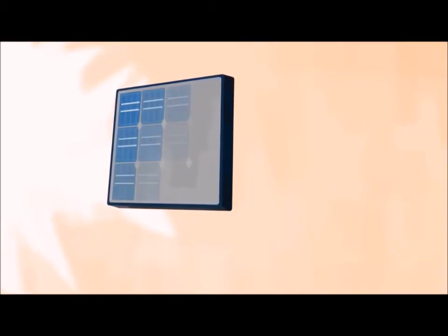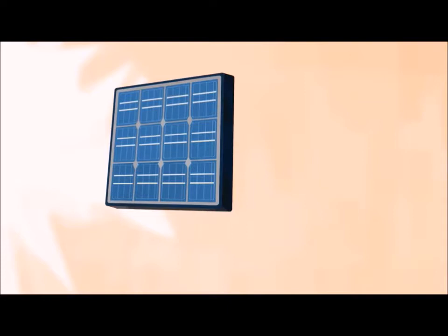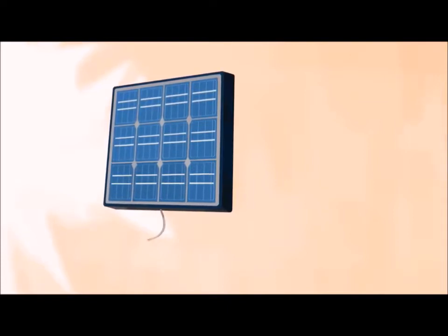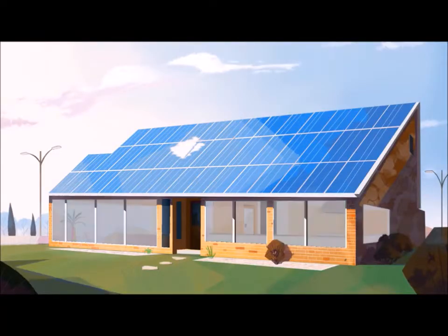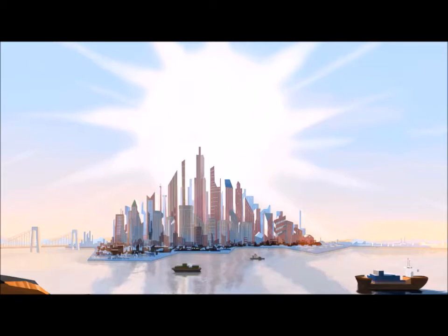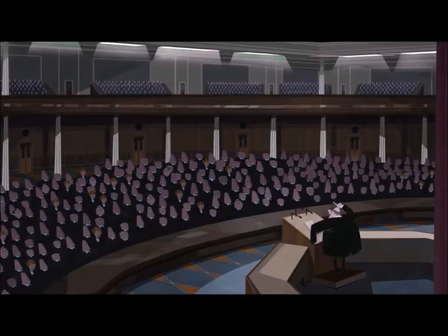Concentrating solar power systems use lenses or mirrors and tracking systems to focus a large area of sunlight into a small beam. The concentrated heat is then used as a heat source for a conventional power plant. A wide range of concentrating technologies exist. The most developed are the parabolic trough, the concentrating linear Fresnel reflector, the Stirling dish, and the solar power tower.